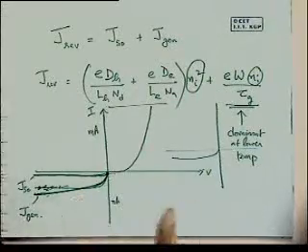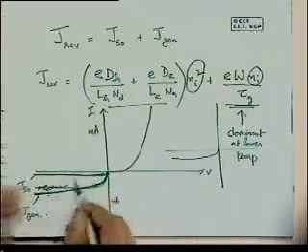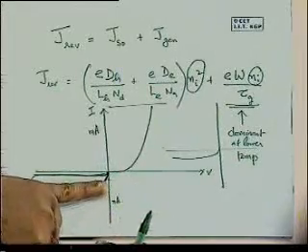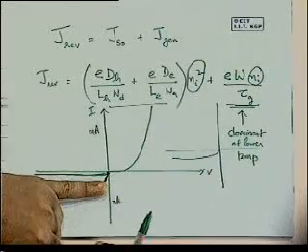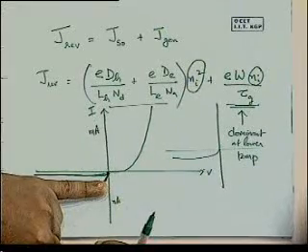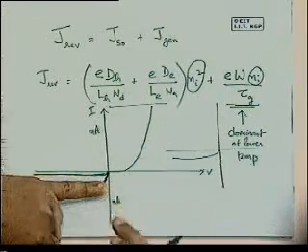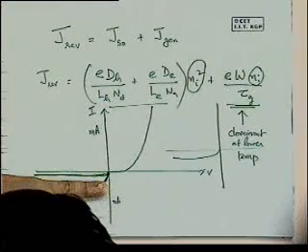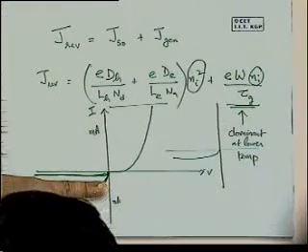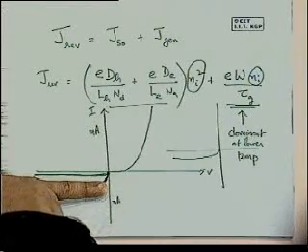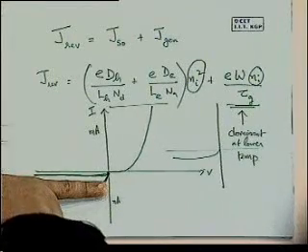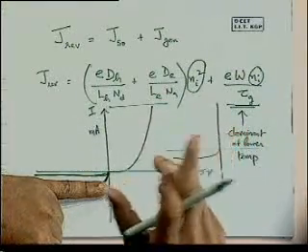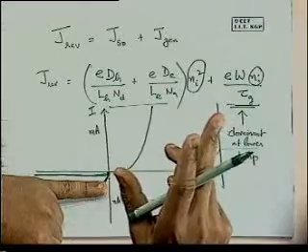All right. What else? I mean, both of these, maybe one or the other dominates. It's not that both of them will be drawn like this. Let's say one is dominant. Let's say that's all you have. It's constant. It's independent of voltage. That would be more or less true for Schottky also. The primary difference we see is that in the case of PN junctions, it involves minority carriers, injection of minority carriers, and then in Schottky case, there's no minority carriers involved.